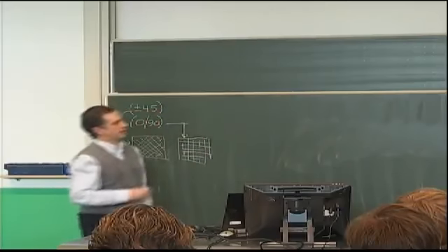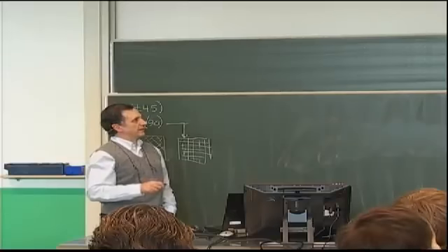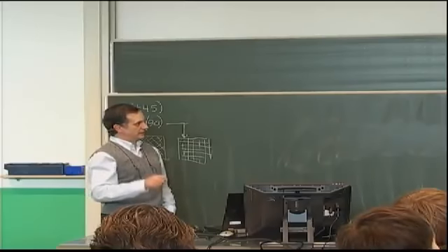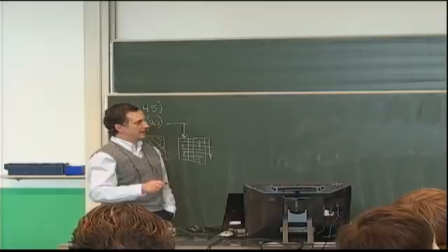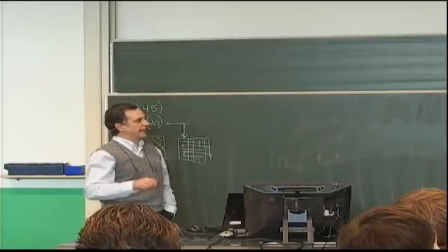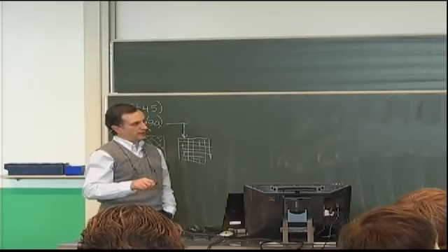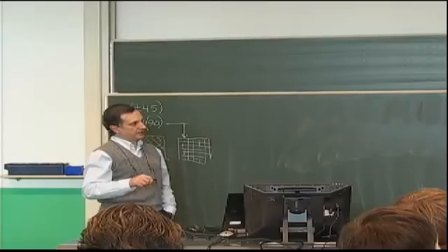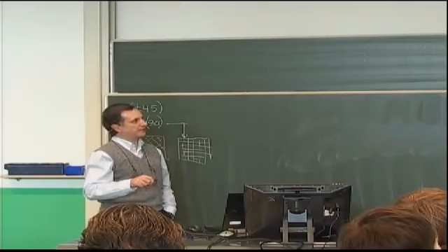And then we take a case of the sigma y stress. So that's sigma y. Remember, my x is going up, my y is transverse. So sigma y is the normal stress in this direction. And again, this is plotted as a function of y over b, at the same location, x over a equals 0.0075.